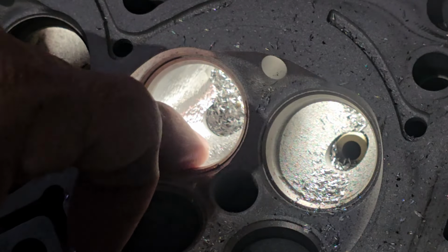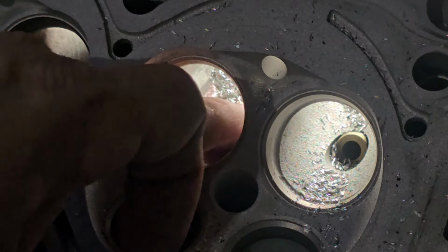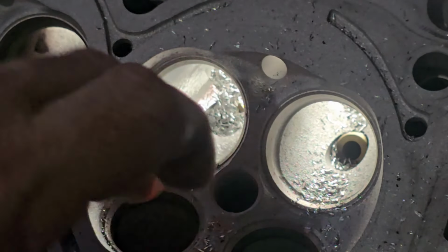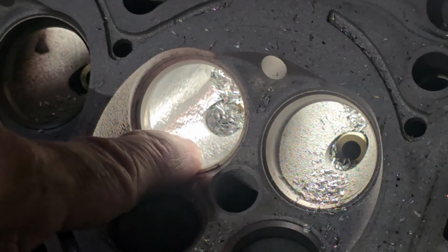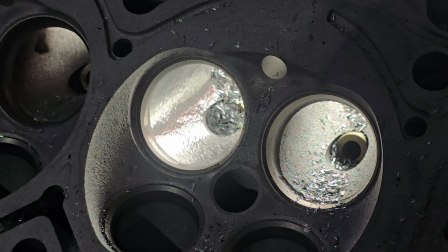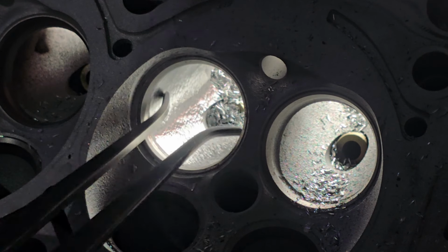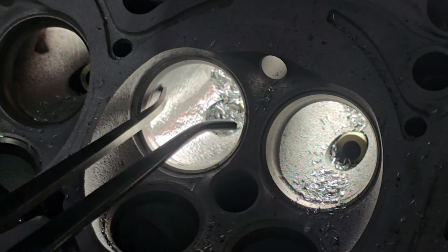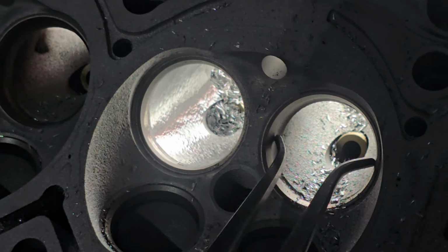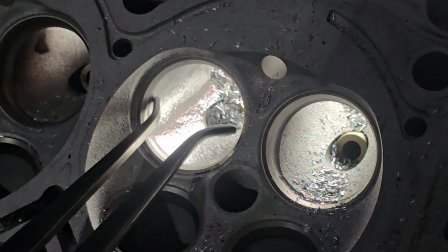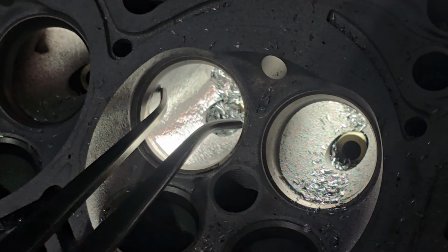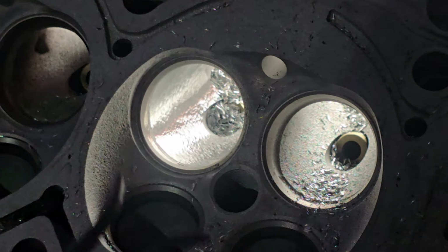So I'm just trying to blend this, and then I'm going to lift that roof slightly around each side of the guide to make more area for the air to turn around the valve. Other than that, we don't want to pull too much out. But yeah, we've got to fix this. So you can see how tight this side is to that side. So that's nearly 80 thousandths. So you can see that falls straight through.